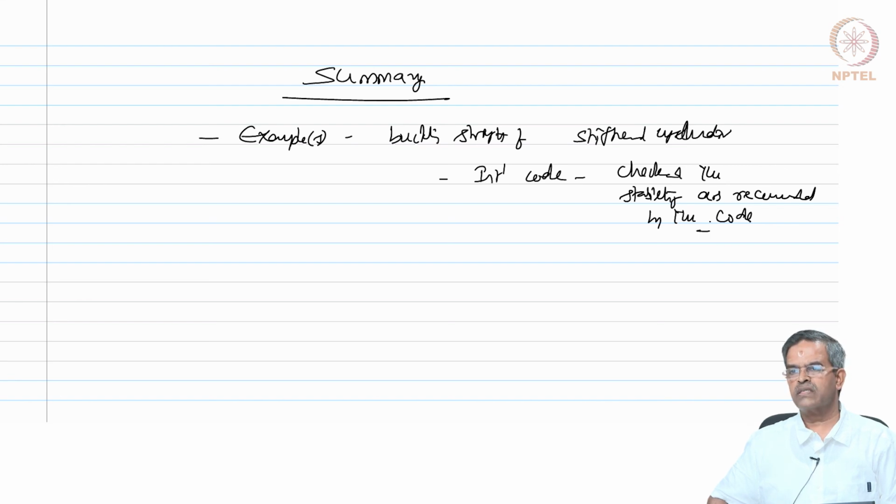So, friends, in this set of lectures on stability, we learned different types of stability. We learned stability is a mode of failure, and we learned the difference between stability and buckling. We derived the stability functions for axial compression, zero axial load and axial tension, and the rotational and translational functions of stability equations from first principles.